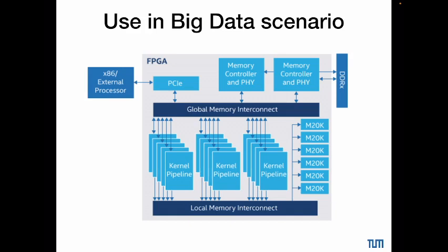Obviously you can also use this, for example, in networks. There's a network interface card, and on the network interface card we could have an FPGA. You want to do direct processing on the data that arrive on the network interface card. So you program the FPGA to do exactly the algorithm you want, so you don't even have to bring the data to the CPU and make the CPU do the computation. You have your FPGA on the network interface card for that. That is another example for speeding up computation with the help of FPGAs.